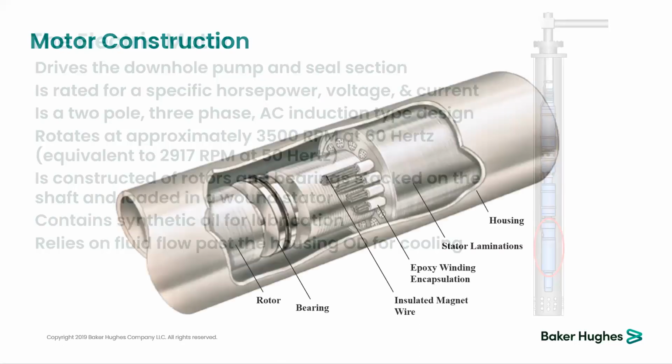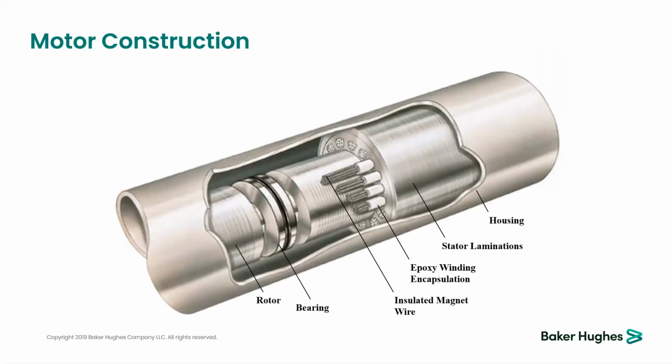This is a photo explaining that the stator is made of lamination stacked together, and the same thing with the rotor, which is stacked with the lamination as provided in that photo. The lamination for the stator is stacked together and compressed in the housing, with large copper bars and more magnet wire in the stator.